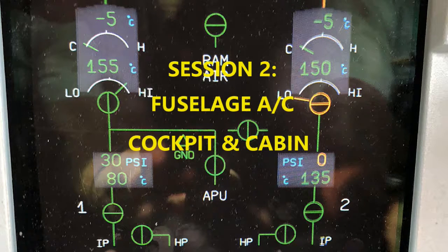The outflow valve is part of pressurization, so you do have an outflow valve that's motor driven, and it has 2 automatic motors, a manual motor, the gearbox, of course, the valve body, and also 2 electronic boxes. Okay, those are the components of the outflow valve. The outflow valve is located at the rear fuselage below the right rear cabin access door. So you're going to access it from the aft cargo compartment through an access panel there. All right.